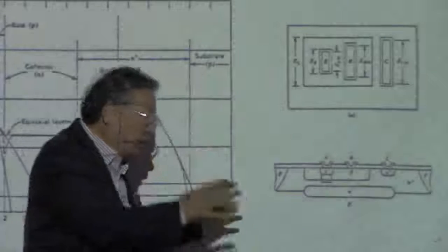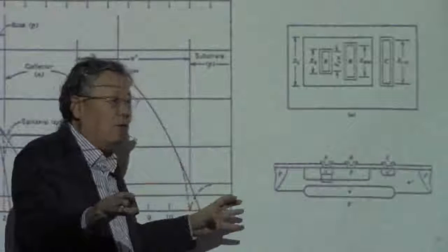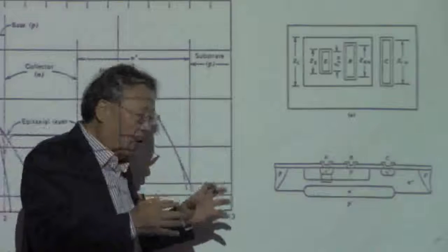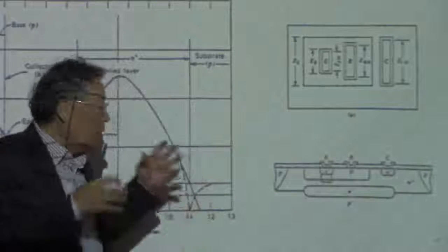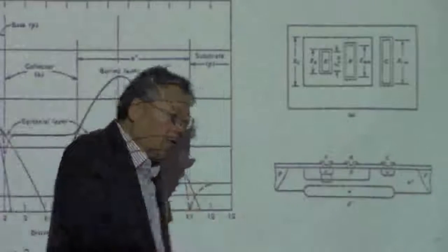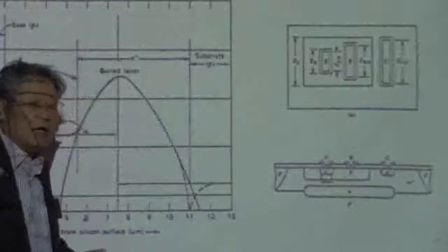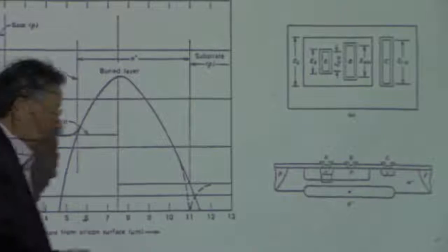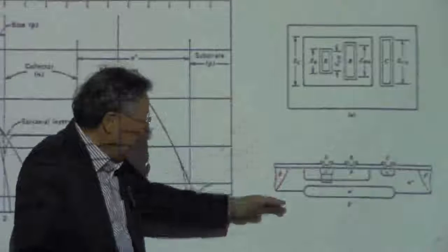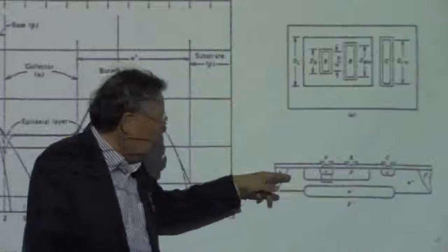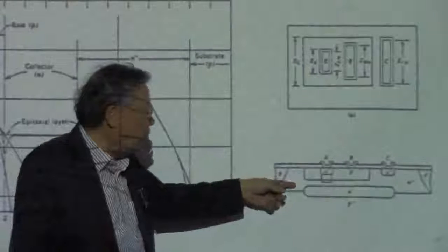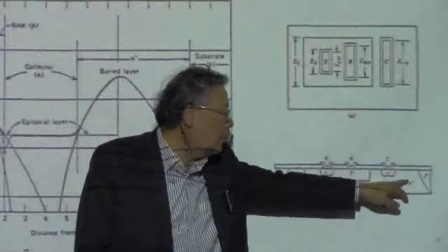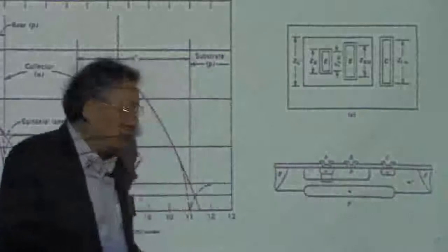So arsenic and antimony have the same diffusion coefficient for the out diffusion, but antimony is preferred because antimony has a lower vapor pressure than the arsenic, so that it is not going to be vaporized during the epitaxial growth. Anyway, and then you have to add some phosphorus during the epitaxial growth to make the epitaxial layer N minus, relative to the substrate.